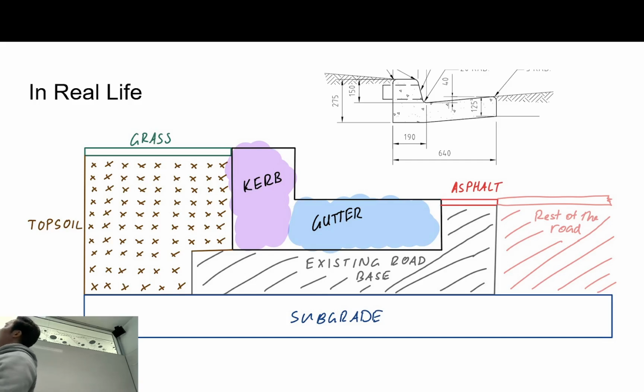Underneath, we actually have a couple of different materials, right? So topsoil is one of them. That's just soil that we use for gardening, essentially. Below the asphalt and the curb and gutter, right? So the curb and gutter is made of concrete. Below that, we have this thing called road base. And road base is essentially just rock that is blasted from a quarry.